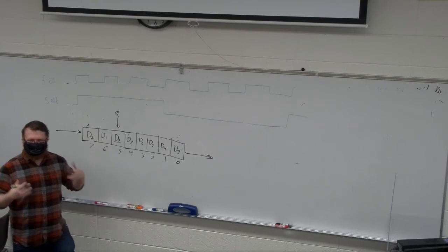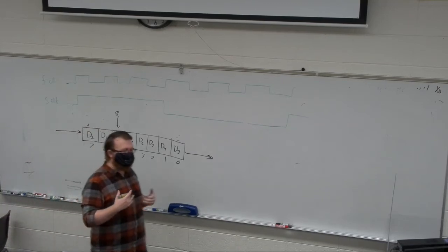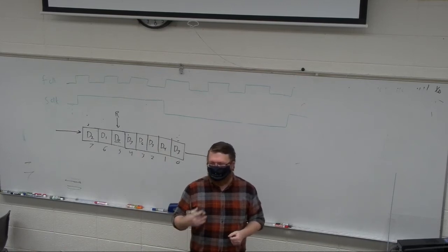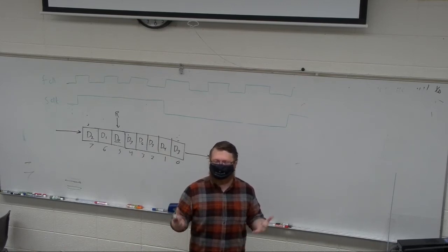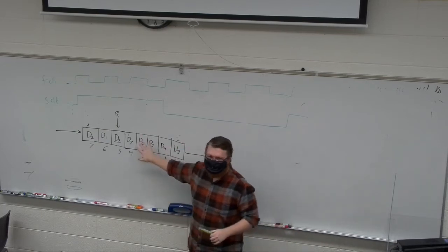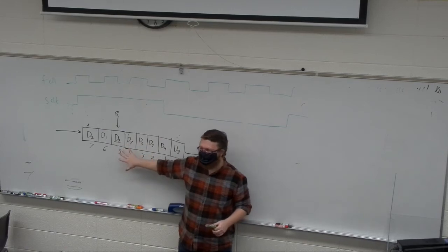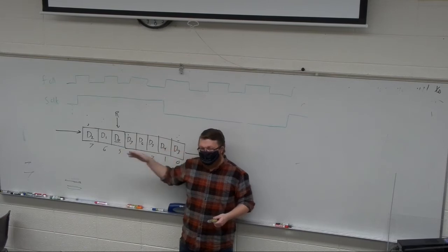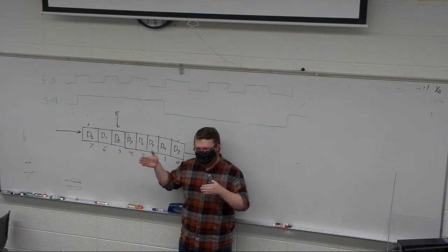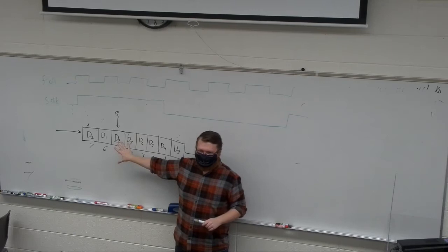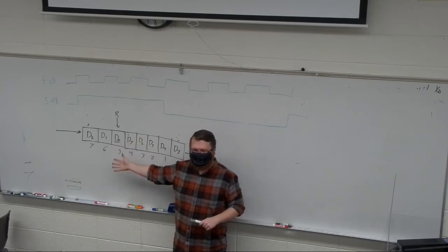So this is synchronous FIFO. This is a good way of storing data while I'm processing it, right? So I may generate it in chunks, slot it into the FIFO. So I could have a parallel load, just like you have with shift registers, right? I could parallel load and then shift out. I can parallel load a FIFO and shift out, or even load FIFOs in chunks, just like you could do with a shift register. So here we're holding data and transmitting it out.